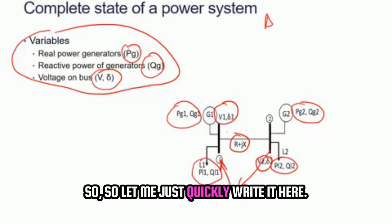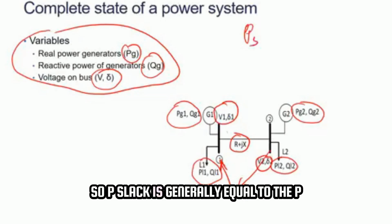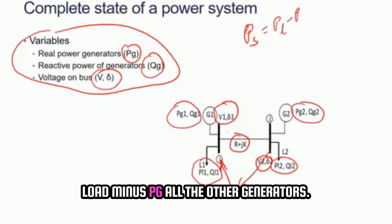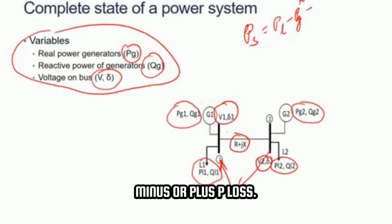So let me quickly write it here. P slack is generally equal to P load minus PG of all the other generators, that is, the PV bus generators, plus P loss.